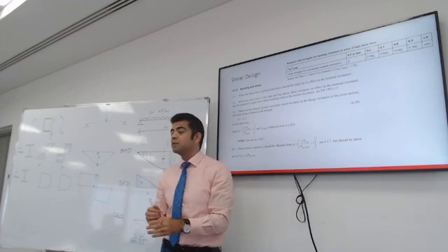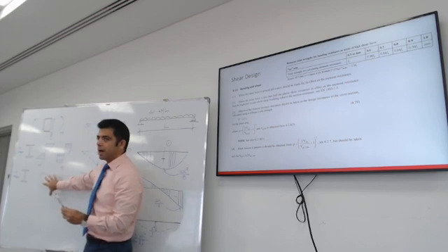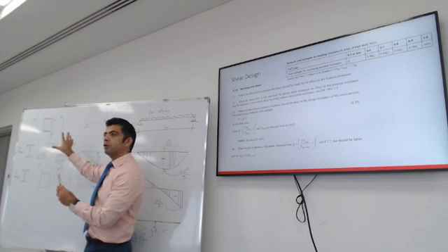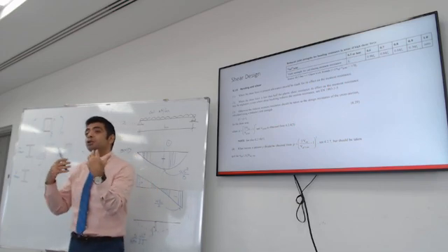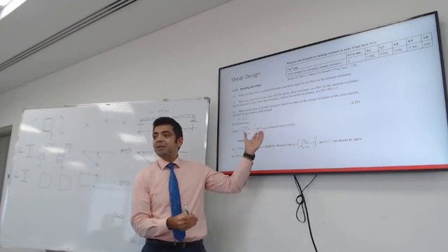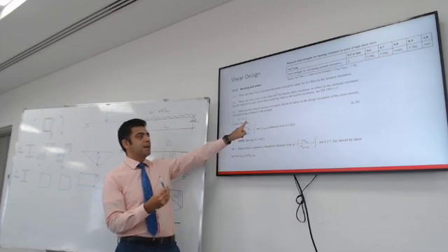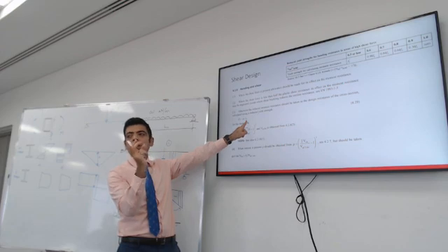In other words, if you have too much shear, do not design the section in bending for the full capacity, reduce it. So how much do you reduce it? The code tells us the reduction equation. You should multiply the yield stress, reducing it by a factor smaller than 1.